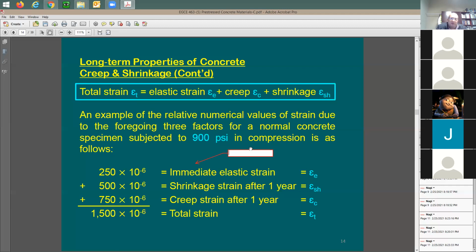Okay, when you increase the concrete strength, would that reduce the amount of elastic strain? Yes. Okay, the strain equals P times L divided by EA, correct? You guys know this equation. The strain equals the axial load that you cannot change, the length of the member you cannot change, the cross-section area you cannot change for a given member.